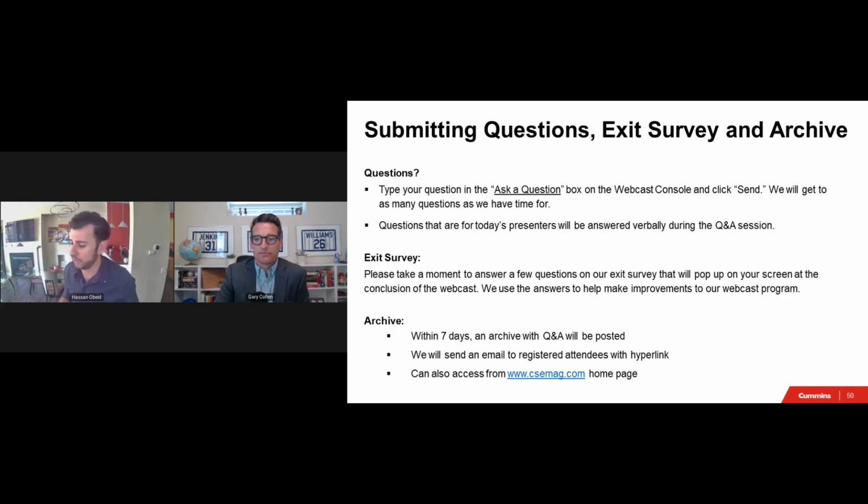And remember, 1558 has UL 1066 breakers, those are power circuit breakers. They can hold the circuit fault for up to 30 cycles. If you do that, then make sure everything between it and the transfer switch, the cables, can handle that fault current. And then you want to specify a short time rating on the transfer switch.